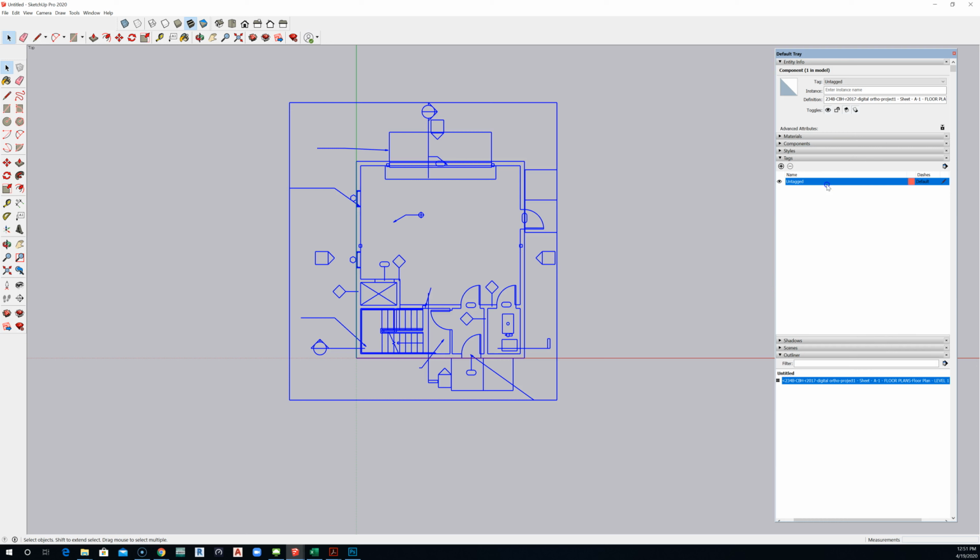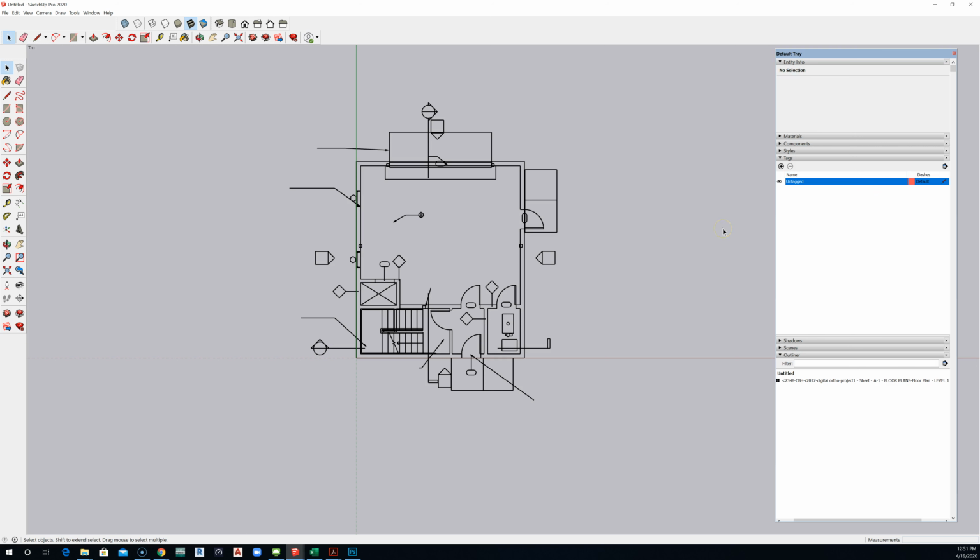So I'm going to go out on a limb and say, similar to other versions of SketchUp, you should always model on an untagged tag and only change the tagged layers, none of which we have right now, but we're going to develop, when you need to control visibility settings for elements that you model.